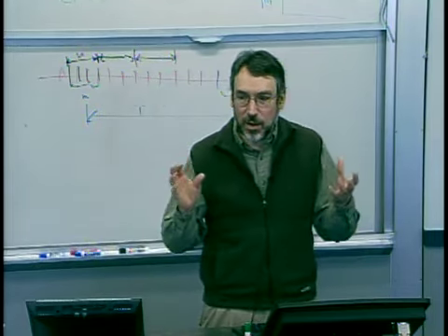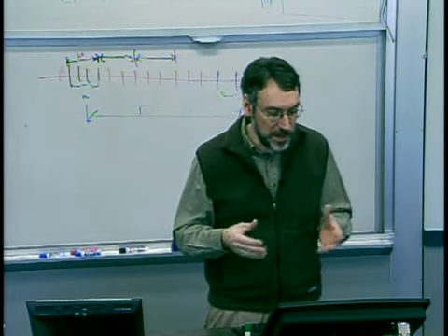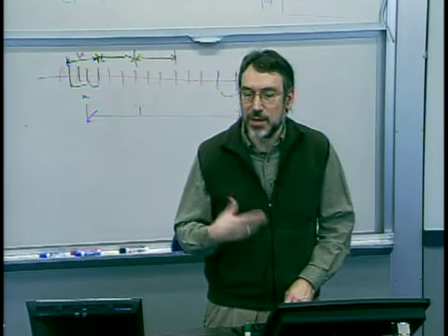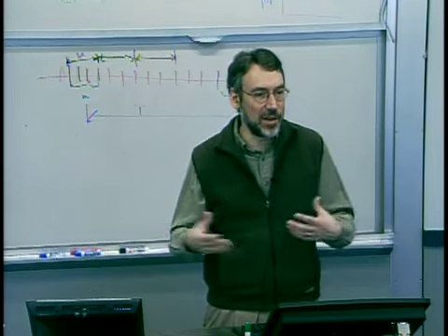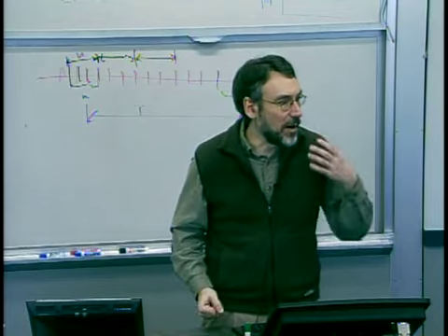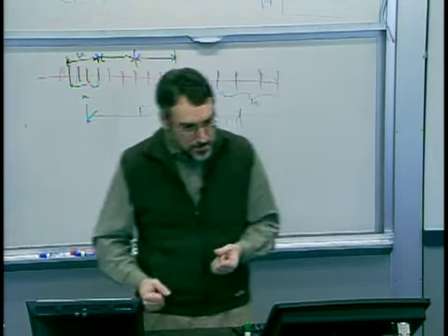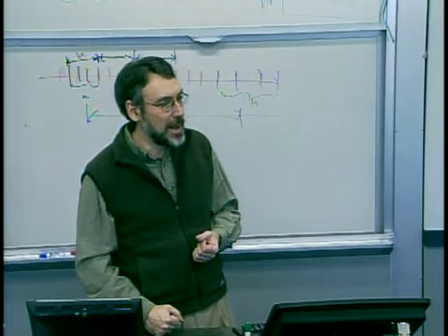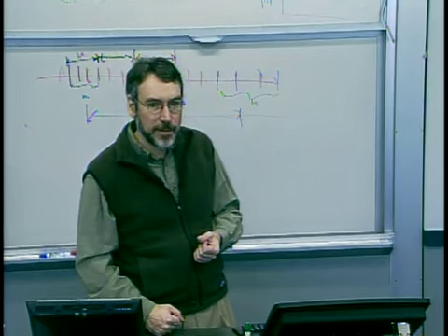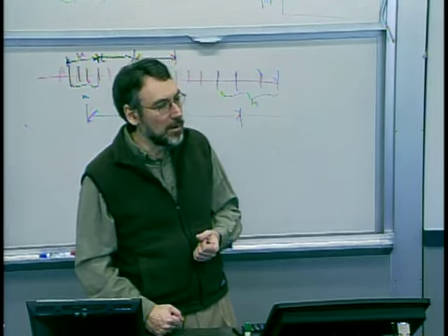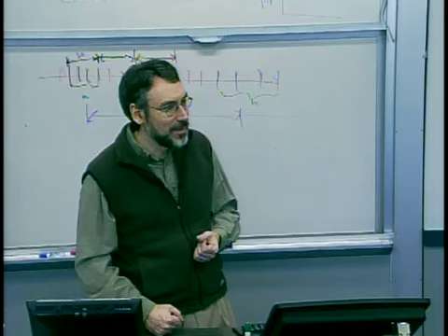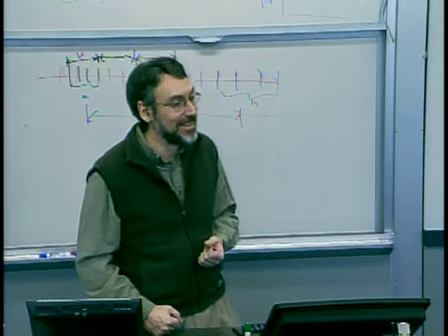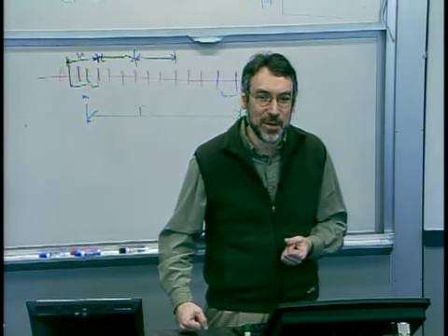To relate the two, a good way of thinking about it is the CP and CPK, or an expected loss function. What's nice about CP and CPK is we basically normalized away, so that if I came up to you and told you my process has a CP of 3 and a CPK of 2.5, you'd go, wow, I'm impressed. That's a pretty good process, or awfully loose spec limits. One of the two. You don't really know.